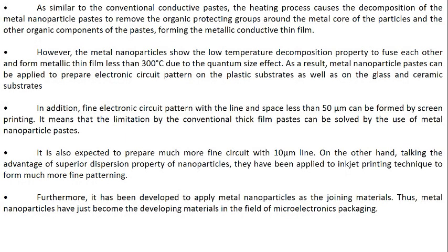Like traditional conductive pastes, metal nanoparticle pastes are heated to decompose organic protecting groups and components, forming conductive thin films. But here's the game changer. Due to the quantum size effect, nanoparticles fuse below 300 degrees C, enabling circuit patterns on plastic, glass, and ceramic substrates.